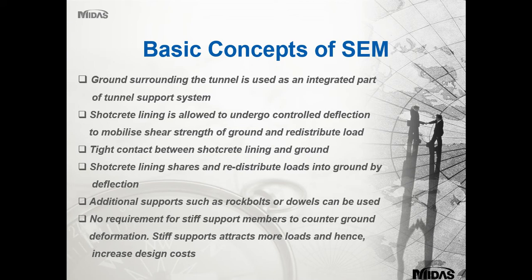So the ground conditions are going to affect the shotcrete itself. As the ground deforms, the shotcrete is going to deform with it, and as it rebounds as well. At the bottom, all the load is distributed to the ground conditions through the shotcrete, and that is going to have a reverse effect on the shotcrete as well.